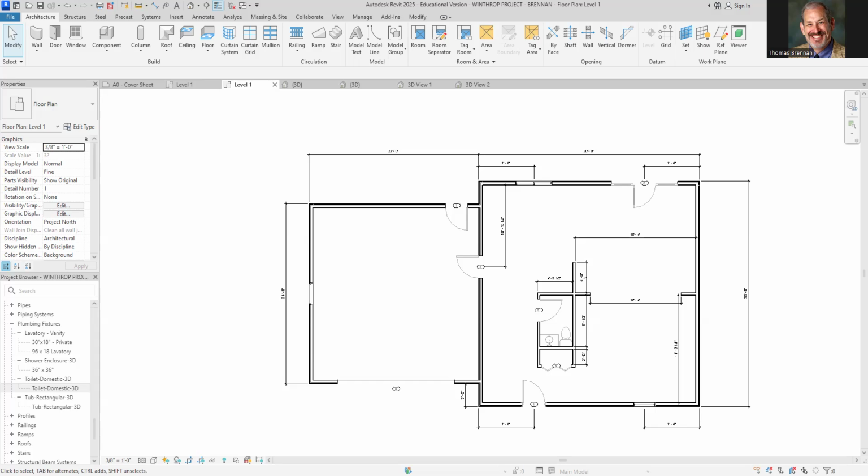We talked about this earlier, but if you click on this right here, I can go over here and pin it. So if I click on this, that keeps it from moving. So that's not going to go anywhere, and the rest of these will move. Now if I go to this, that needs to be 6'10" on the inside. So now I can force it, because now the other one won't move. So it's 6'10". Now that just moved that down there. And now they've got this 9 foot 11 and a half. See that? So that's a little trick you can do right there.